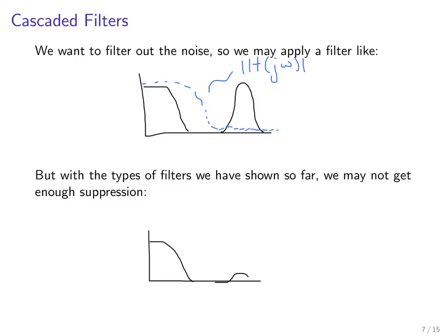Maybe we have some significant amount of noise left that is still degrading our SNR significantly. So this would be our filtered noise after just a single filtering operation. And obviously, the closer in frequency the noise is to the signal, the worse this problem is going to be. And the difference between 10 hertz and 60 hertz in practice is quite small. Okay?